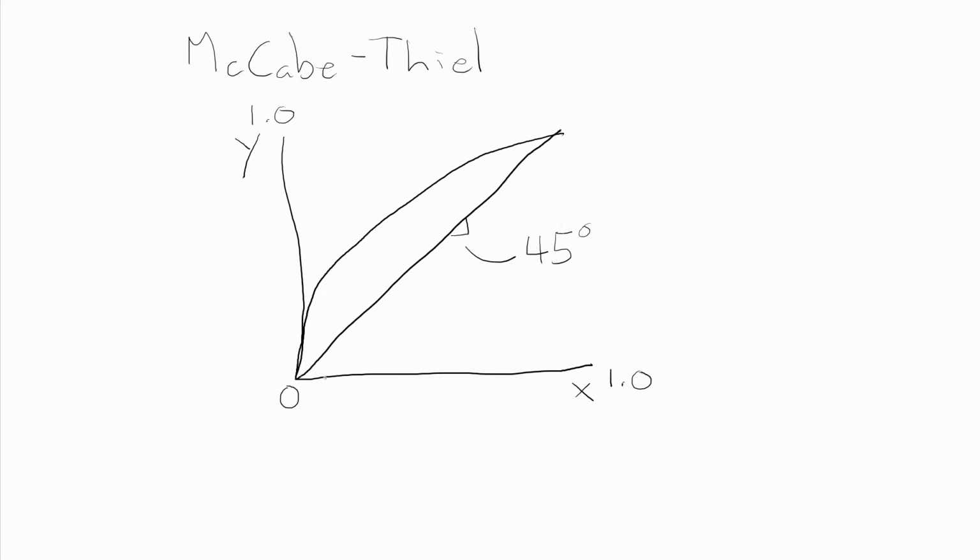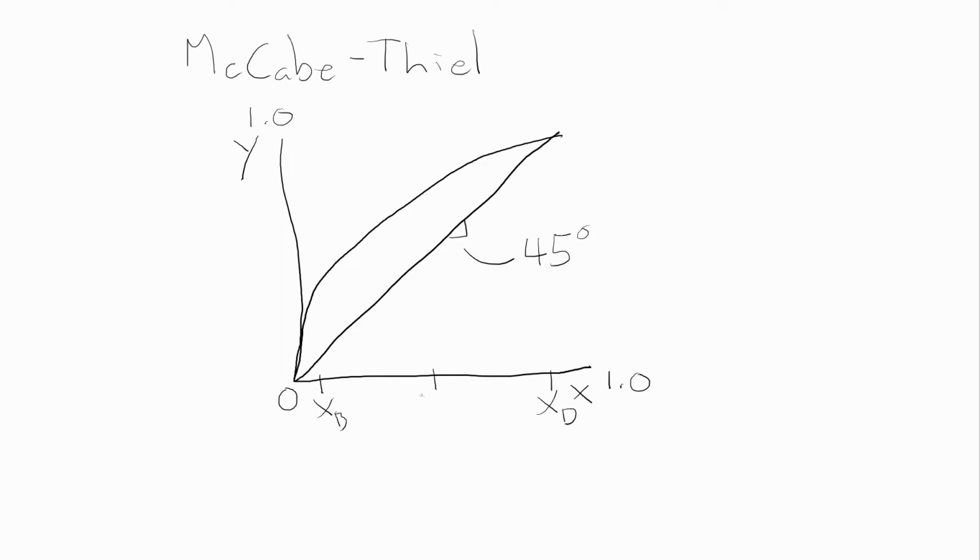So the first thing that we can do is identify 3 points. We can identify the bottoms composition, the distillate composition, and the feed composition. This gives us the 3 points at which our two operating lines for the rectifying section and the stripping section, and our Q line for the feed intersect the 45-degree line. The next step is to draw the Q line. We know that the Q line is going to intersect the 45-degree line at this point, at ZF.